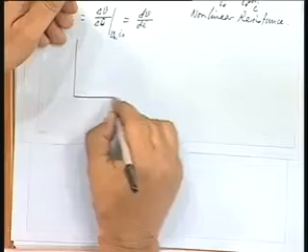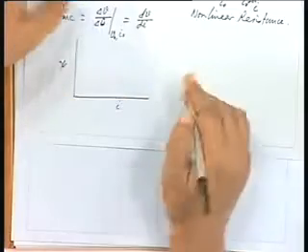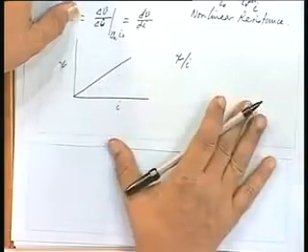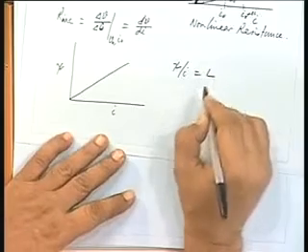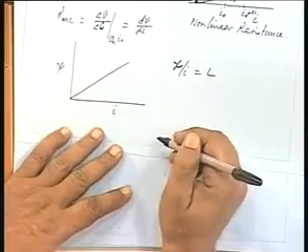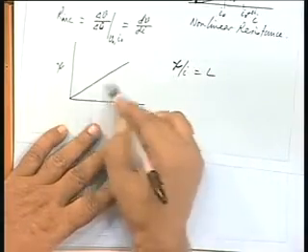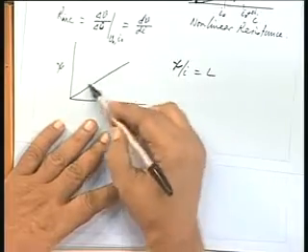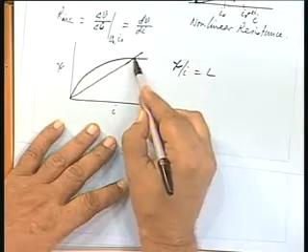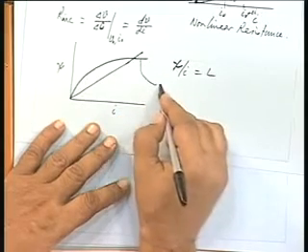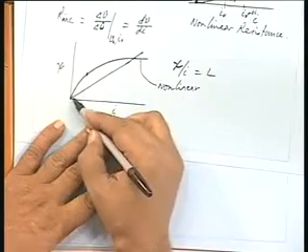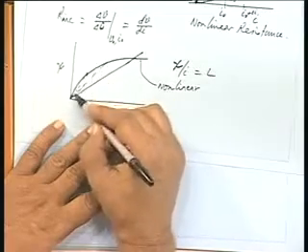So an inductance will be given by this ratio if it is a linear one. There is flux linkage per unit ampere. Now it is not necessary that it will always be a characteristic like this. There can be inductances where the variation of the flux linkage may be like this. Can you cite an example? This is a nonlinear characteristic. That means once again here also the flux linkage per unit ampere keeps on changing with the value of I.